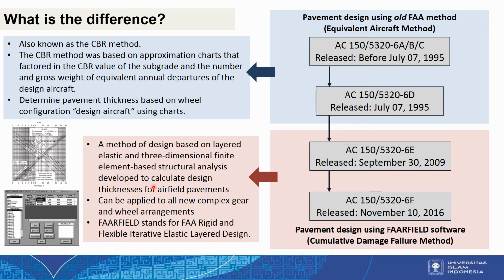Because if we use the old FAA method, we depend on the charts, and the charts are different for any wheel configuration. Nowadays the wheel configuration of an aircraft is really complex and not as simple as in the old times, so we need software that can be applied to all new complex gear and wheel arrangements. FAARFIELD means FAA Rigid and Flexible Iterative Elastic Layered Design. This is the difference between the old FAA method and the FAARFIELD software.